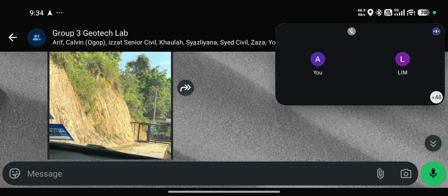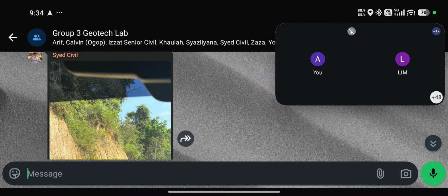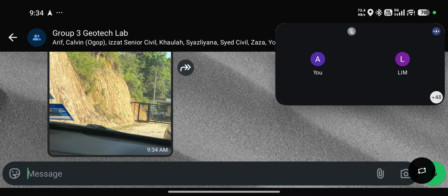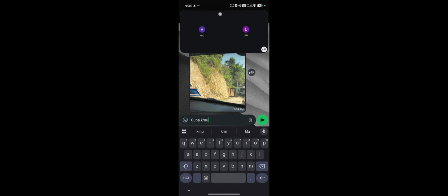Very simple, but you have to calculate epsilon first. Epsilon is the square root of 235 divided by your steel strength. What did I say our steel strength was, just now?